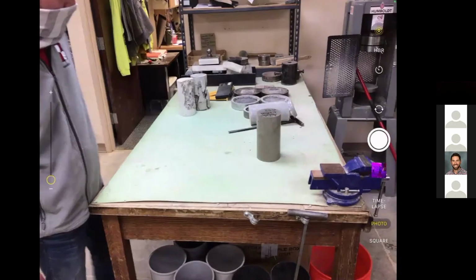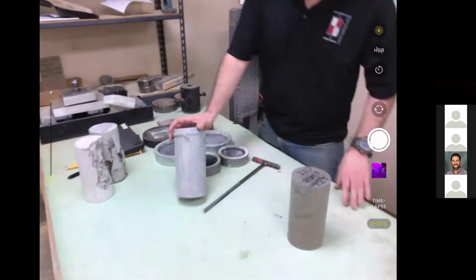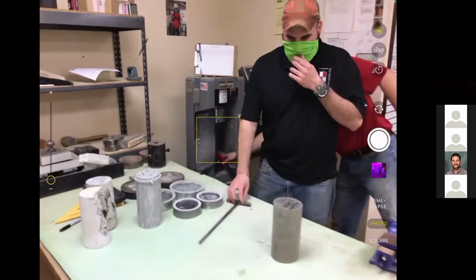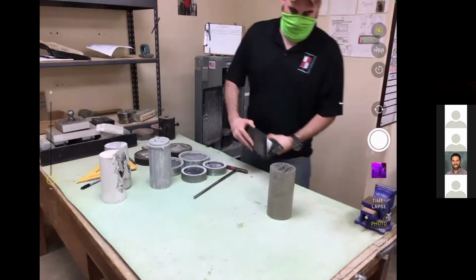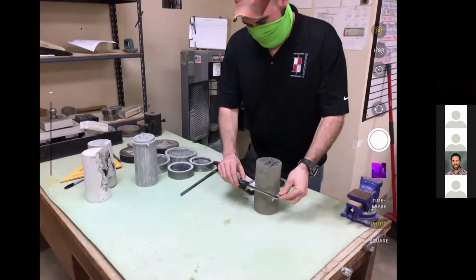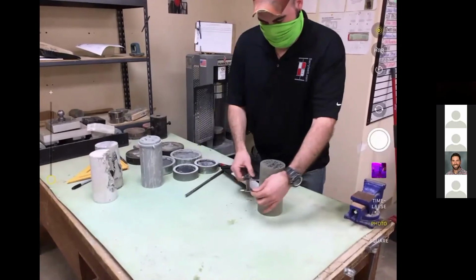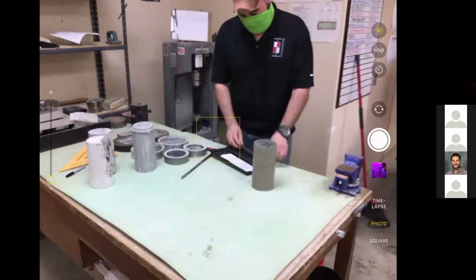All right, guys, I'm back. I do the ACI compressive strength for this office. So when it's time to come break cylinders, first thing we always do is ensure the right diameter. Okay. First thing you do, about mid-height, take 2 readings, 90 degrees from each other, make sure it's 4 inches. Both readings are 4 inches.